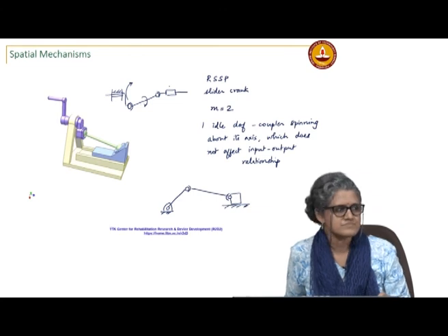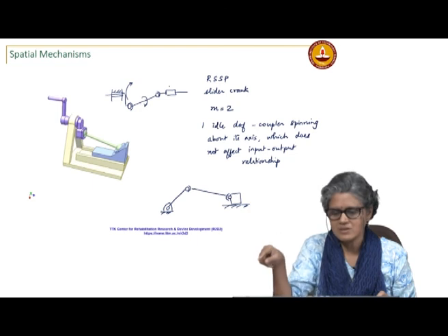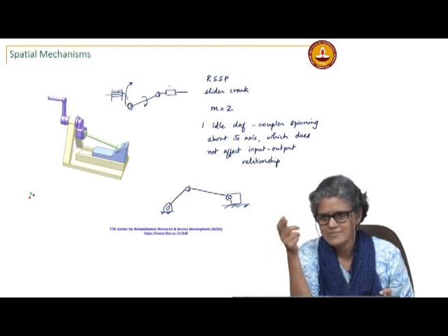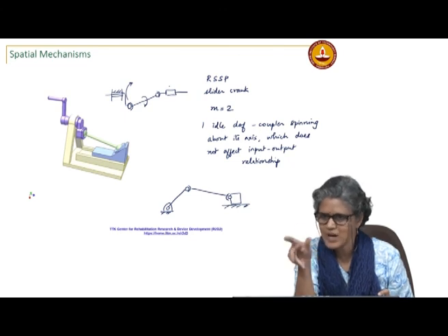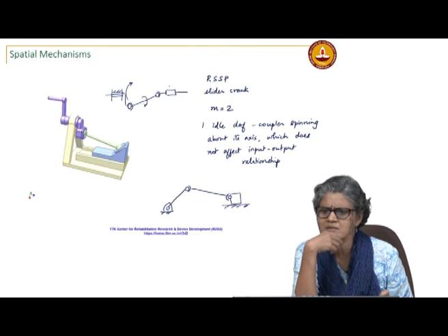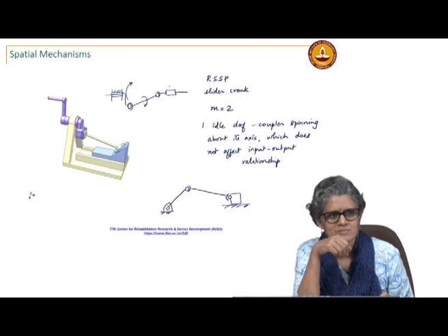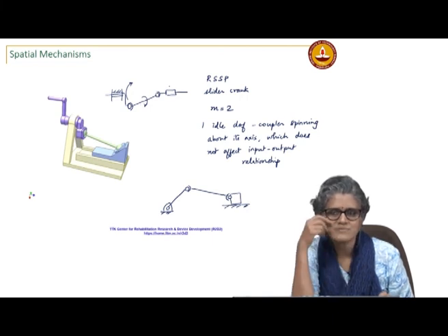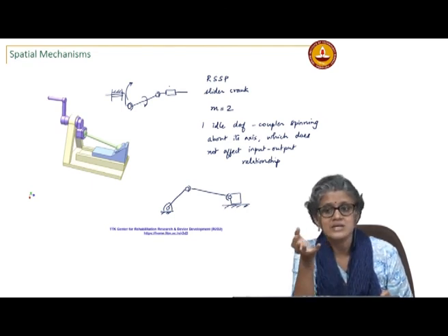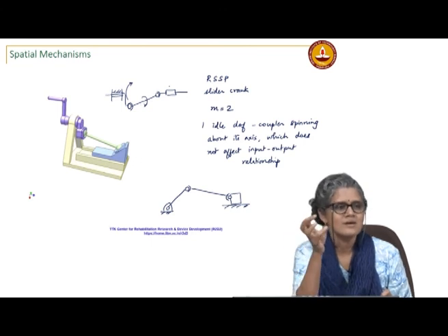How is it a 3-link? It's still 4, right? Violet, white. See, you could still have a 3-link mechanism in 2D when you have a pin in a slot. If you have a higher pair, for instance a cam and follower, that is a 3-link mechanism, and it is a planar mechanism. When we talk about the mobility Grubler's criterion, we say specifically that it is for simple hinge joints.